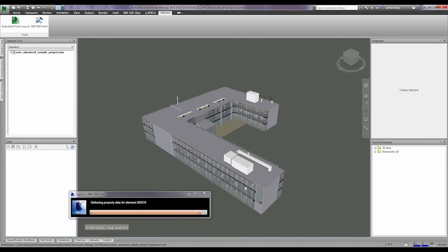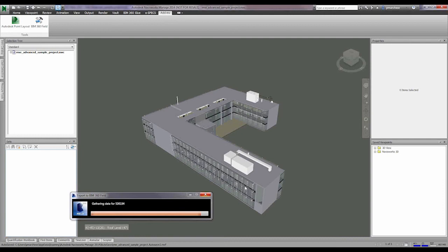But if what you're going to be synchronizing with is Navisworks, so people have given you the files, you've coordinated them, or you want to upload from here instead, what you would actually need to do is create sets. It doesn't matter in Navisworks if you're using search sets or selection sets, but you would need to make a set. That way when you upload this to Field, it understands how it needs to break things down.